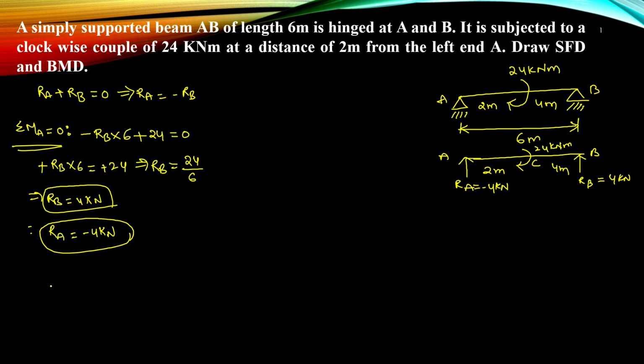Shear force calculation. So our heading is shear force. So let's quickly do the shear force calculation. We will start with shear force at A. What is shear force at A equal to? Shear force at A will be equal to the reaction at A.